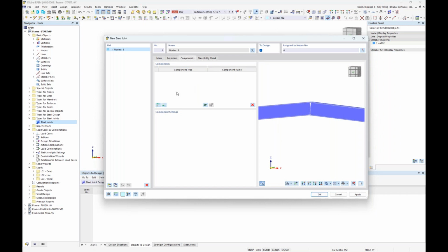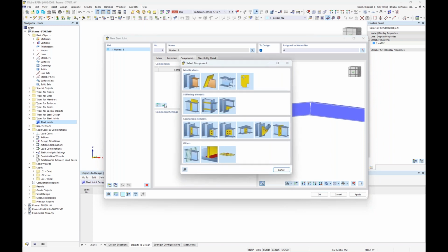And we could certainly individually do this with our connection database here, our component database. And we see each one of these components that we can individually input, such as end plates, or we can input fin plates, cleats, maybe plate-to-plate connections for beam splices. We also have stiffeners and haunches, and then we have some additional modifications up here that more so relate to the geometry. So we can make member cuts, or we can add in openings or notches into our beam elements.